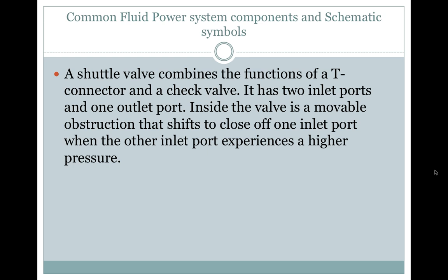A shuttle valve combines the functions of a T-connector and a check valve. It has two inlet ports and one outlet port. Inside the valve is a movable obstruction that shifts to close off one inlet port when the other inlet port experiences a higher pressure.